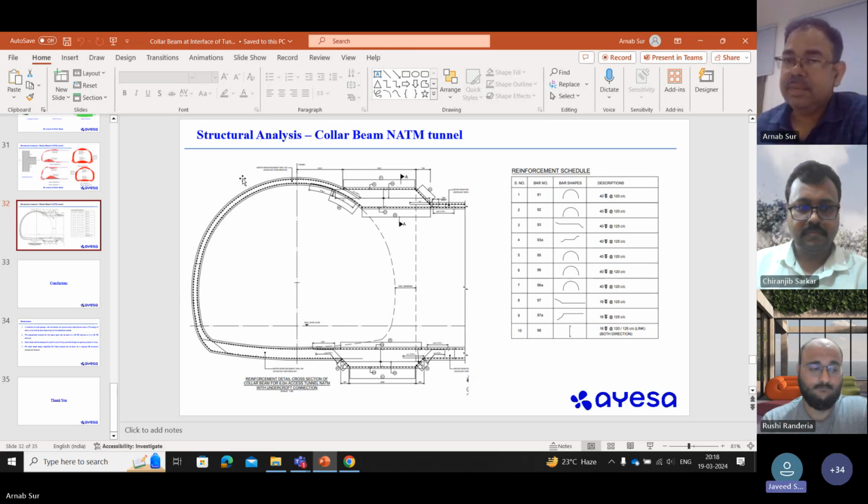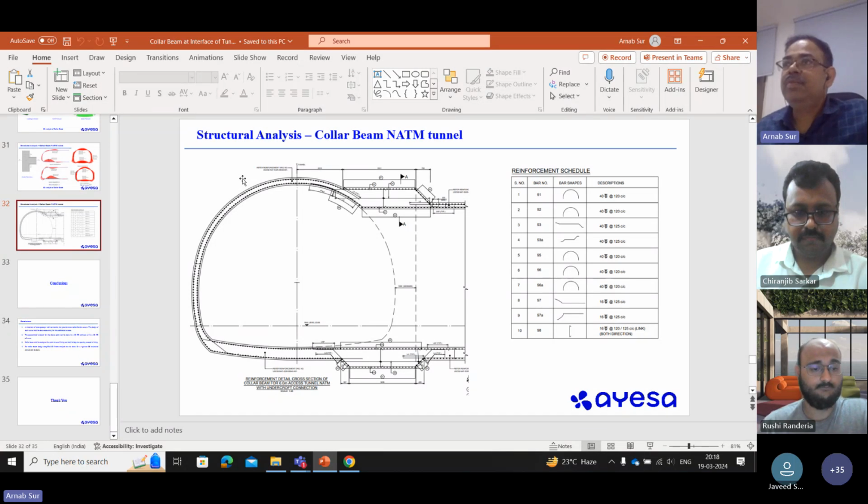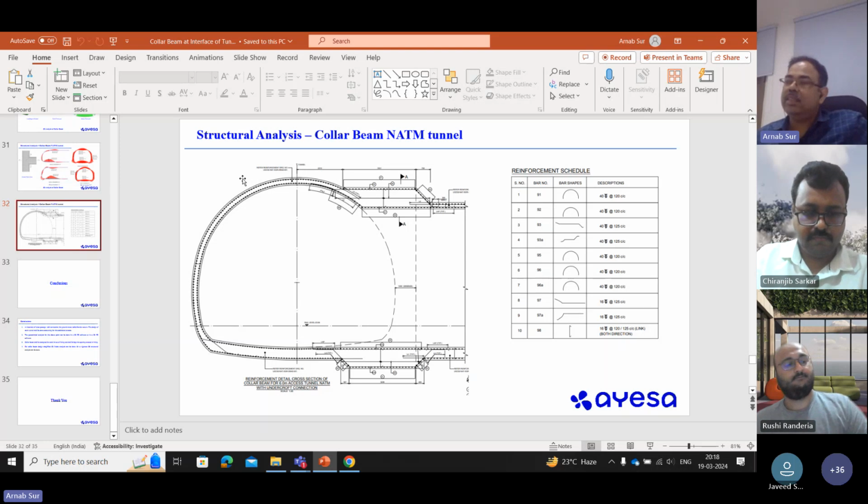But sir, the area of reinforcement will be low. When compared with the area of concrete, the area of steel which you have designed will be less. The area of concrete is higher than the area of reinforcement of steel. Then how can we ensure that? No, that cannot be a problem, because that area you don't require as an RCC section. That is additional concrete you are doing. So that is not a problem because you are not utilizing that section as a part of the RCC section.